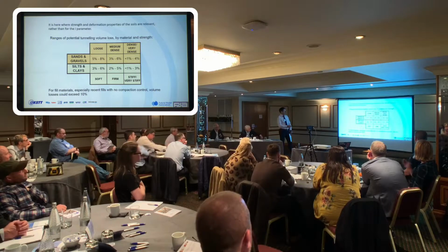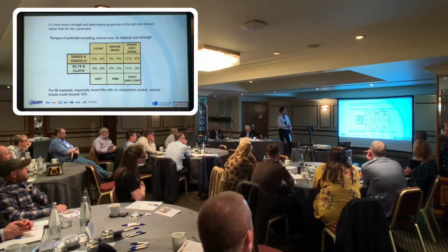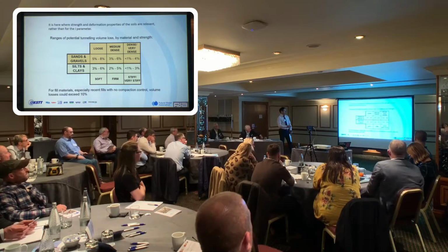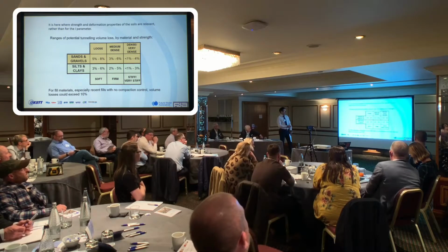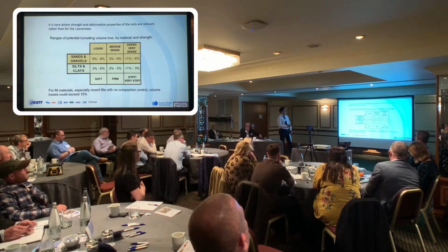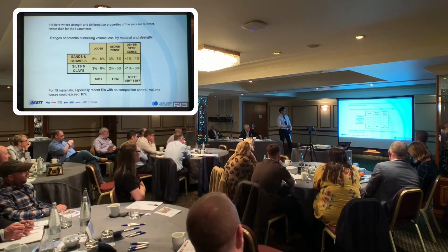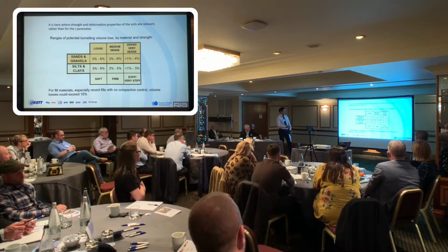If you've got loose sands and gravels, that's probably the worst case condition. It's like an egg timer or an hourglass. If you turn it over, the sand disappears down the hole. Whereas if that was filled with clay, it wouldn't go anywhere. So this is where we can have a bit more input into the actual calculation and have a bit more confidence in the values we're presenting.